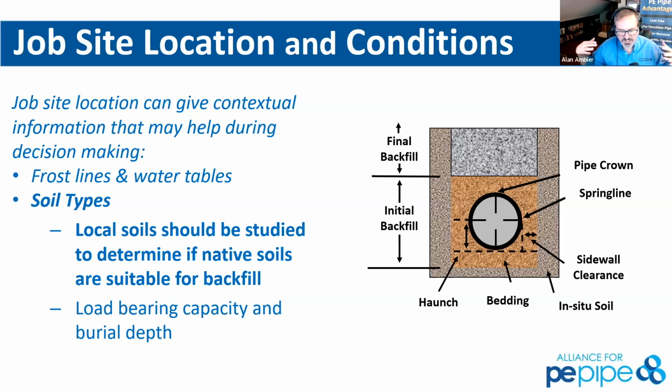Obviously, the elevation control, that inflow that we're looking at for the line of the gravity sewer and the line of the storm sewer, there's a limitation on depth that we can achieve for the lowest depth that a pump station can handle. Pressure pipe doesn't have that issue, as it's always under pressure, so it'll be a little less deep than the gravity or the storm sewer, but still below the frost line. As far as conduit is concerned, for telecommunications, they're probably going to want to try to stay lower, or higher in depth, but really it's up to wherever they can find a good spot. Thank you.